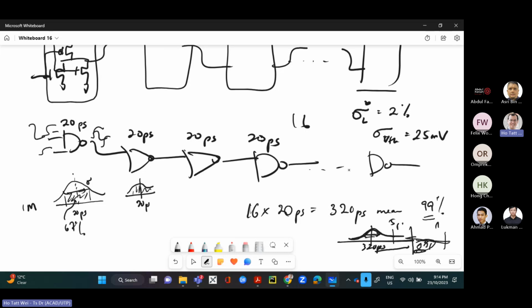So the reason we're doing all of this estimation is because you can estimate the effect of process variation on the spread of delay, and you can use this statistical modeling to actually say what would be a realistic parameter for me to choose in order to achieve a certain yield. I want to meet a certain yield.